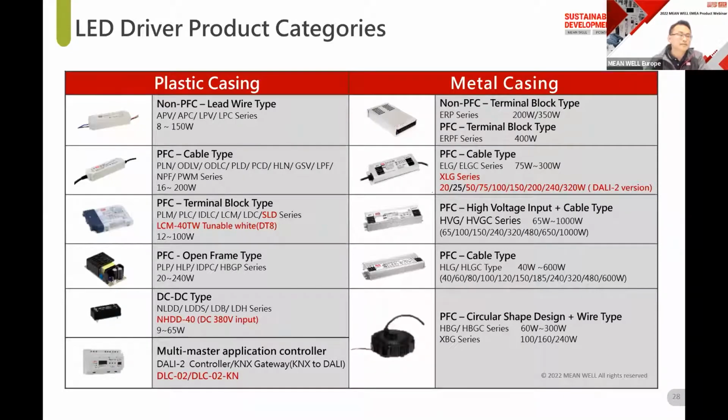The next category is LED drivers. The left side is plastic casing and the right-hand side is metal casing. I would like to point out the new models in red. The LCM 40TW tunable white complies with the DT8 standard. It has a very low minimal dimming level down to 0.2%.